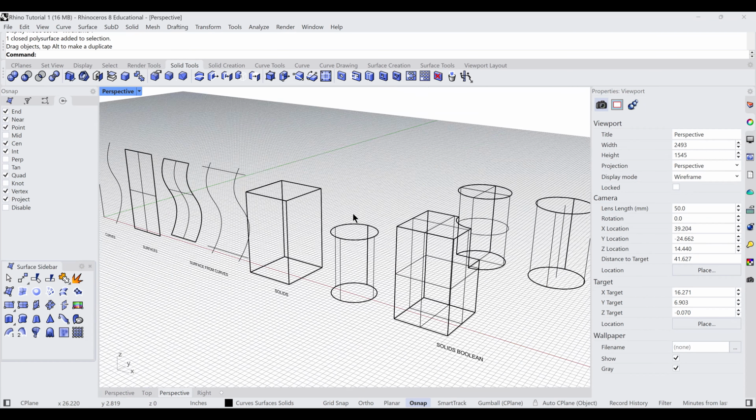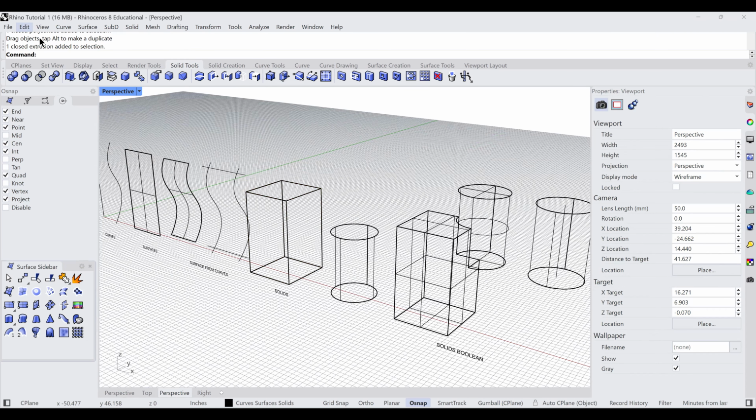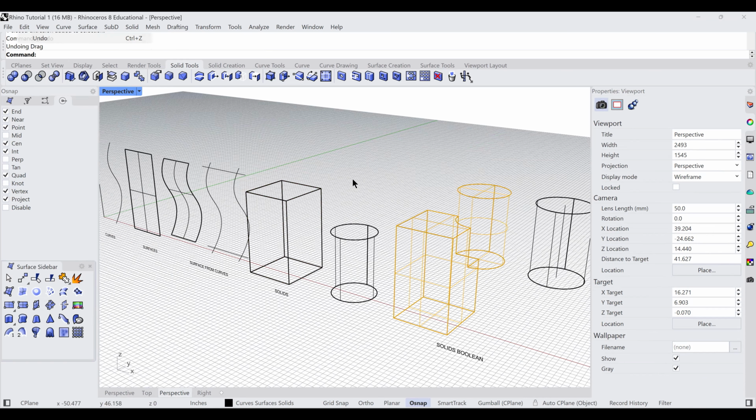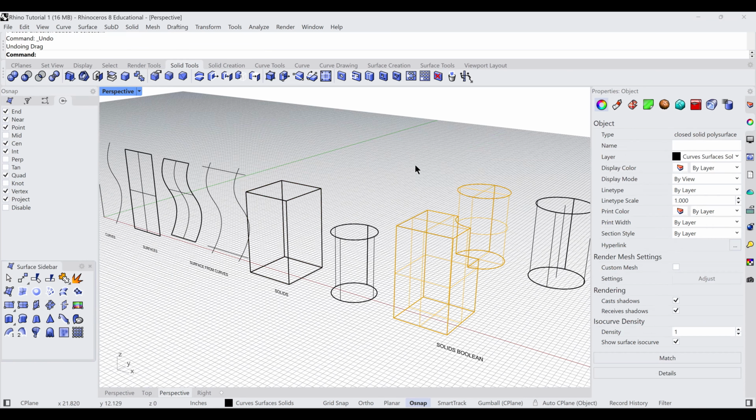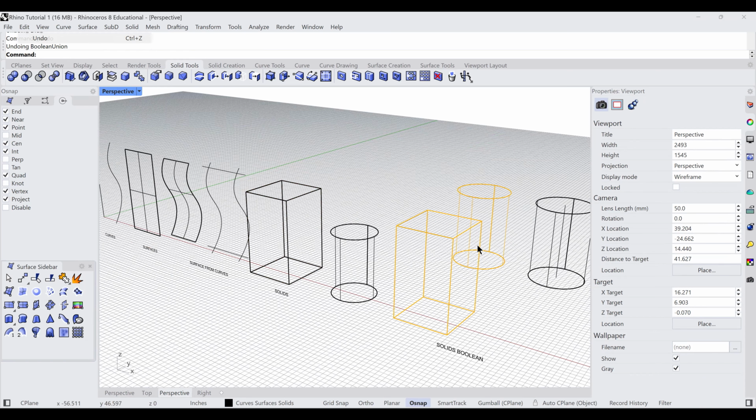It's a little bit of a designation as you build and manipulate things. The ISO lines may appear sometimes. This is just a plain extrusion, so it's not going to show up at that point. So let me just undo that, and you can see how the parts came apart inside. So let's undo. Now I'm back to these two objects.